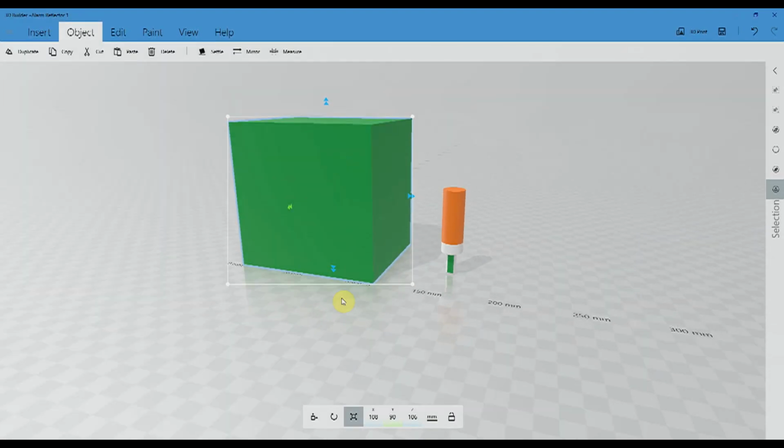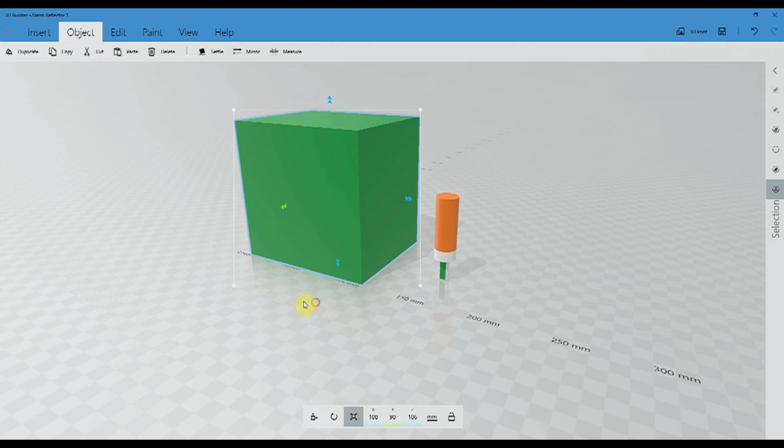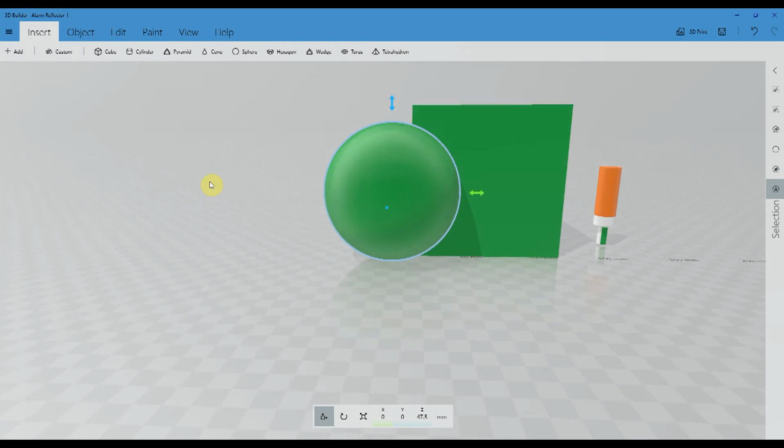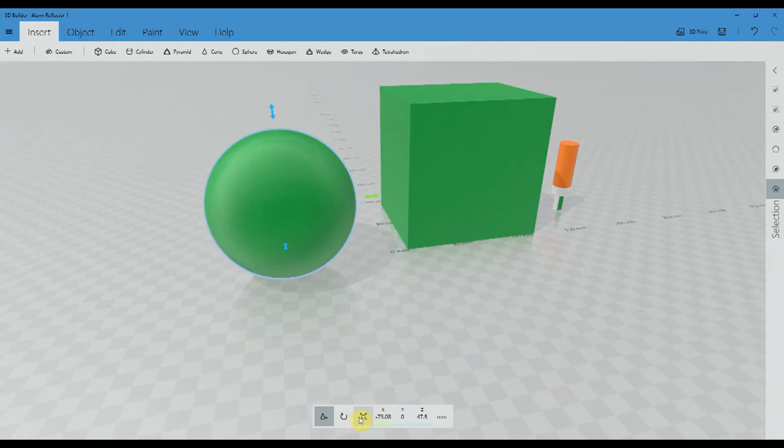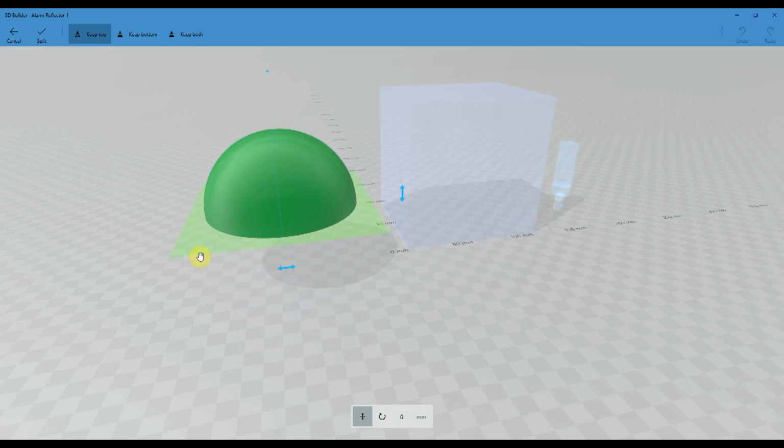Now with 3D Builder, there's several ways of changing shapes and moving them. You can grab on the little arrows that lurk around the shapes, or you can type in sizes, dimensions and positions in the box at the bottom like I'm doing here. I've decided to start by making the reflector. That's some sort of point to start, some sort of reference. It's a bit daunting otherwise.